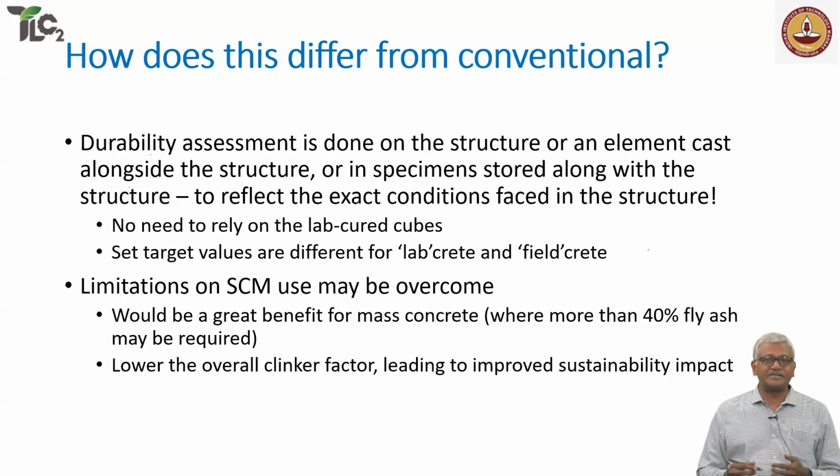Then I went to the lab and I said, okay, you may have made cubes from the same batch, show me the cubes. They got the cubes. Cubes were in perfect condition. They tested the cubes. Cubes gave perfect strength. The 3-day strength, which was expected, was given by the cubes. So what happened here? The site concrete had some tampering. What tampering? Addition of additional superplasticizer to ensure that they got workability at the time of placing the concrete.